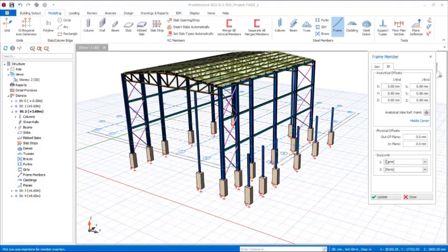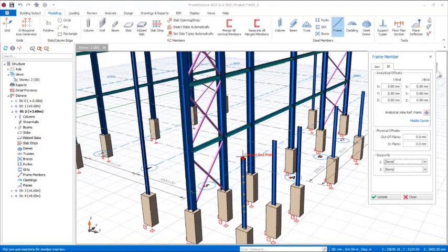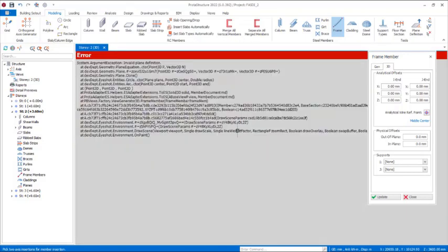And then if you come over here, you have a support here. If maybe you want the beam to have a support, you can actually select your support here. In the last lesson, we were able to create a support, pin support, and then a default fixed support for the foundations. All right, but for this we wouldn't have any support, so we want to place it right away. So what you just need to do, head your hand over the end of this stanchion and click once. So once you click once, you have to direct your hand to where you want to fix it.